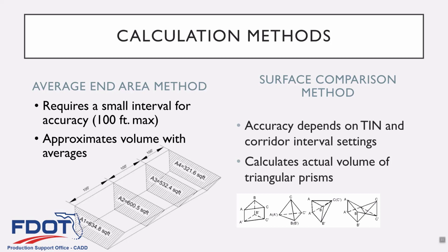It's kind of lopsided, and the curve opens up on one side, so the interval is like 105 feet on this side and 95 on the other side, and it's throwing things off, or the curve might even be tighter than that. So there's a few examples like that. You start to lose accuracy with different configurations and different project-specific issues.